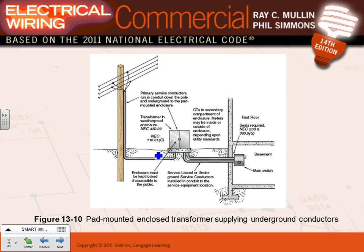Okay, here's a typical service, guys. Please, guys, look at the picture. If you look at that one here, I have primary service conductors coming in. That's owned and operated by the electrical utility here. Everything here is owned and operated by the electrical utility. Right in here, it becomes my CT cabinet. Can you guys see that? Primary service conductors. And then from here, this is my service point.